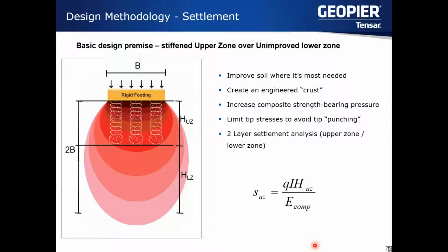And normally when we're talking about ground improvements, there's usually three things that we're trying to improve. So settlement is the first and probably the biggest one, what normally controls. The second's allowable bearing capacity, and improving the allowable bearing capacity of the site. And I mentioned that's normally somewhere in the range of 4 to 6 KSF, but can be as high as 7 KSF in the right soil conditions. And also global stability, if we're dealing with embankments or MSE walls, or if something's built on a slope, making sure that there's an adequate factor of safety for global stability.